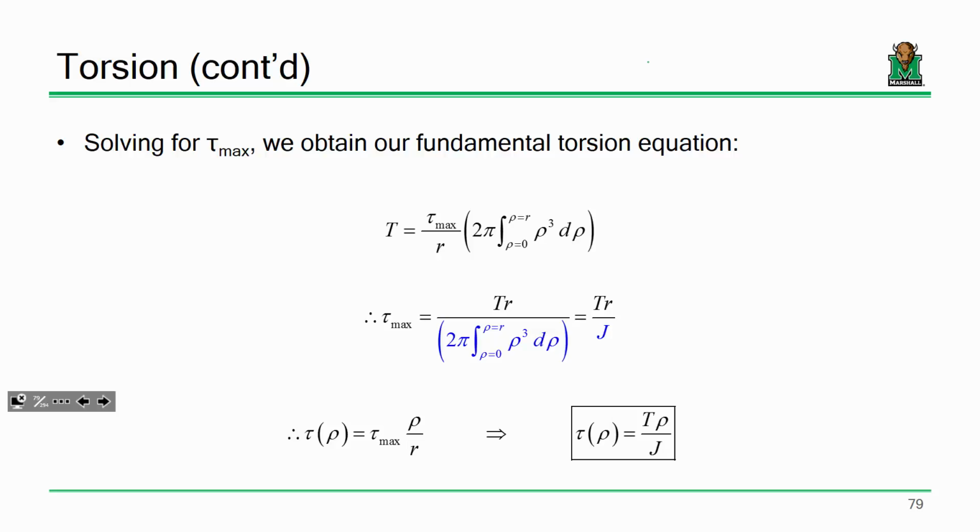And what do I mean by section property? A section property is something like area. In other words, if I have some bar and I use my secret weapon, samurai sword and or lightsaber, I cut a section through that bar and I look at that bar has certain properties. Let's say it's a circular bar. That circular bar has certain properties. For instance, it has an area, right? Pi r squared. It has a centroid, right smack dab in the middle of the circle, right? Make sense? That shape, or that cross-section, has certain properties. Hence, we call them section properties, okay?